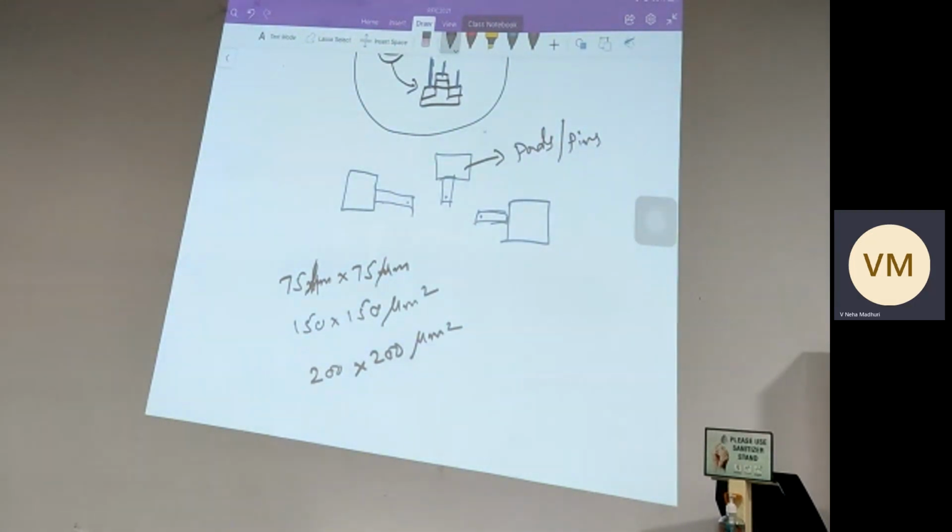So to the gate, I want to give some input. To the drain, I want to give some VDD, supply voltage. Where will I get the supply voltage from? Either I can get that from a battery, or I can make a power supply, right? You started the lab, I think the first lab, you have seen the power supply, right? So that's a DC power supply. You want to give that DC power supply, that is called VDD, to the drain of your transistor.